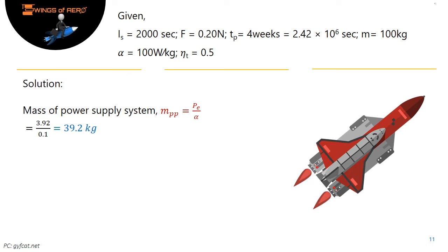Next, find the mass of the power plant. Specific power is considered to be proportional to thruster power and reasonably independent of total useful propellant mass. Its value depends strongly on the type of electric thruster and somewhat on the engine module configuration design.